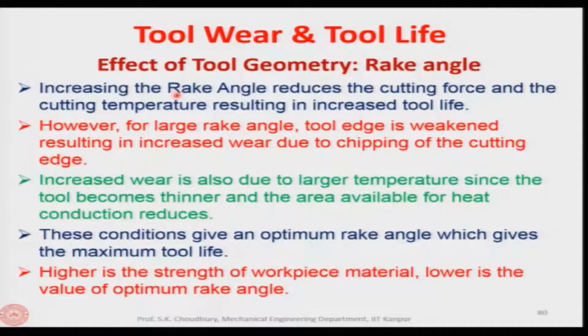This we have discussed while discussing the selection of the rake angles. So, increasing the rake angle will reduce the force, it will reduce the cutting temperature and the tool life will be increased, and vice versa. However, for a large rake angle, the edge is weakened, resulting in increased wear due to chipping of the cutting edge, and the tool life decreases. Therefore, there is an optimum value of the rake angle at which the tool life will be maximum.